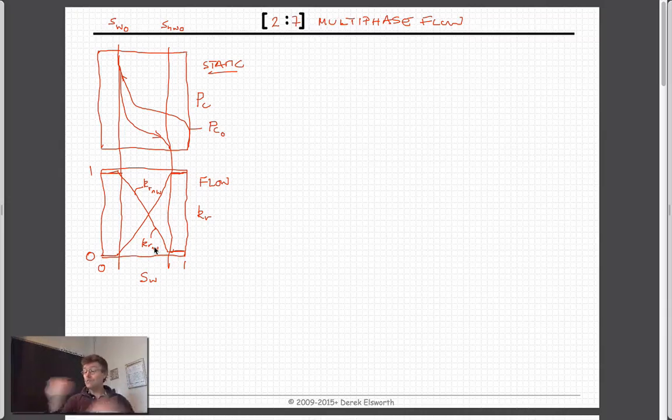Those are really the key concepts that underpin everything we've talked about: how stuff gets into place initially and sticks there, the battle between gravity and interfacial forces, and if we then apply pressure gradients or head gradients, how that stuff is then mobilized and removed at some rate.